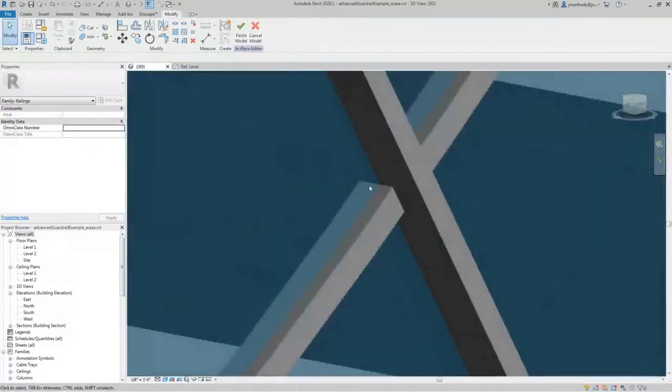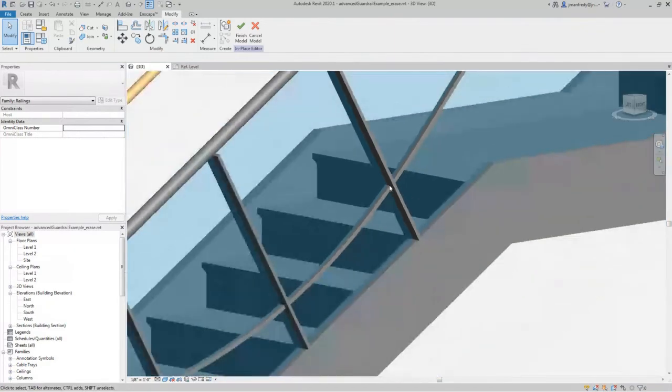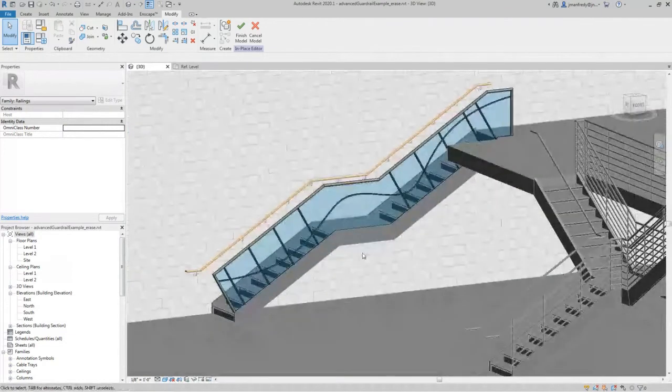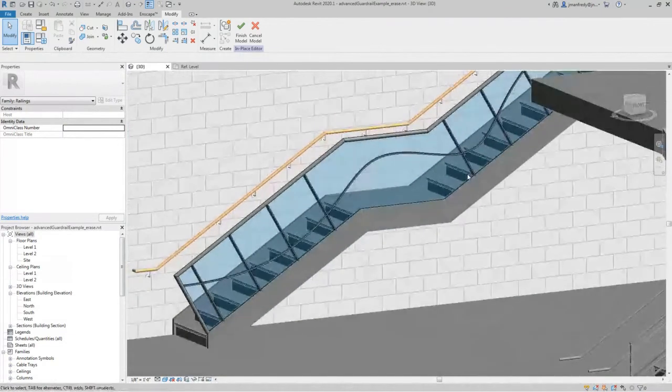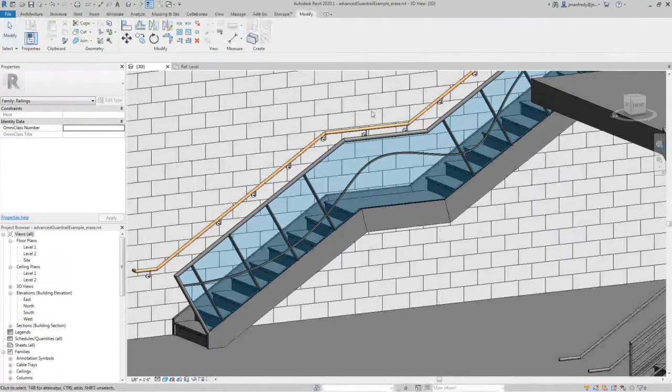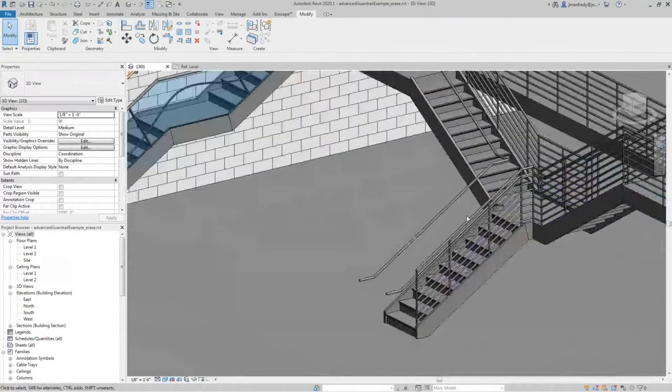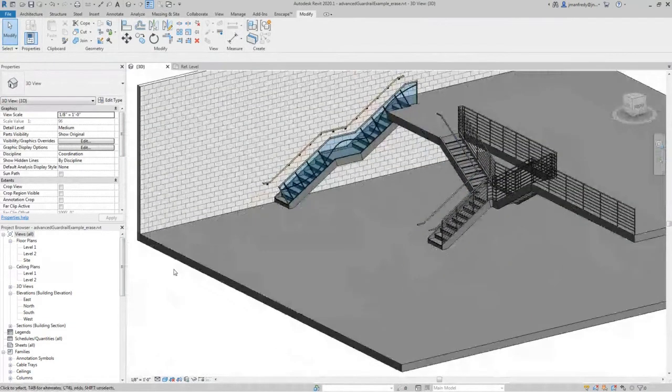It pulled it out. See? That distance right there moved out. So you can decide exactly what shape and what thickness and height you want this to be, or just draw it as a separate file. And lo and behold, you've got an even more custom ramp, or rather, a stair. So those are the designs I wanted to mention, the design capabilities that Revit has when it comes to making railings. The rest of this stuff is just a matter of dealing with the stair command.